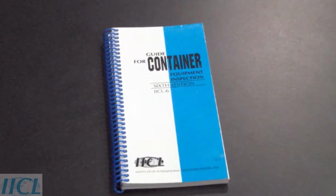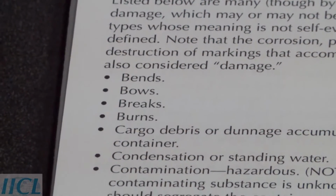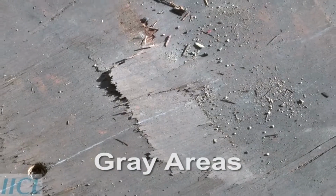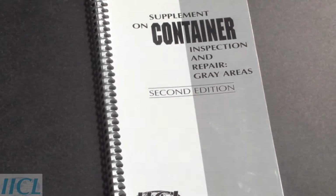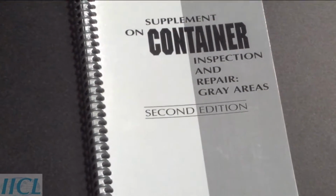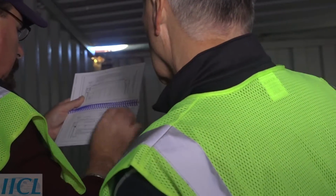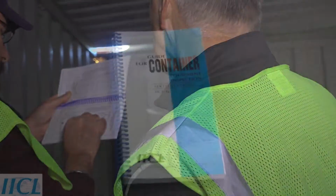IICL 6 primarily covers measurable damage, but there are types of damage, such as the plywood floor delamination shown here, that cannot be measured. These are commonly called gray areas. The IICL gives some guidance for inspecting gray areas in the Supplement on Container Inspection and Repair, Gray Areas, 2nd edition. But in practice, evolving commercial practices and owner policies generally guide the treatment of gray areas.